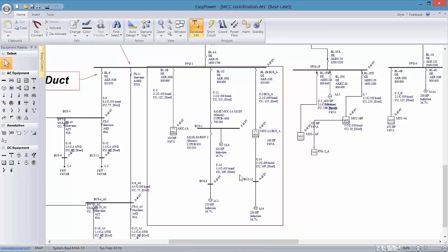In the center, I have a discrete or separate devices comparison, where bus 1 would be effectively the main MCC bus, and the breakers and downstream loads are comparable to what I set up in the icon. And then the third illustration is a combination where we've outboarded a high load, one of the largest loads from the MCC, and I'll go into the reasons why we do that and what benefits it gives us.